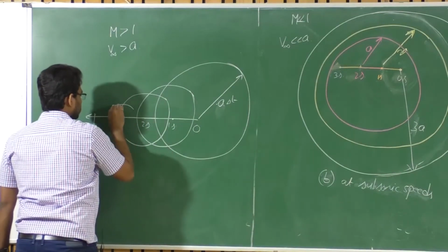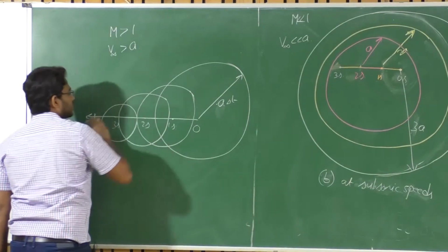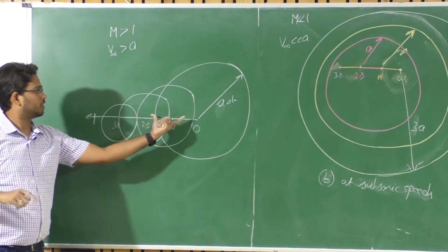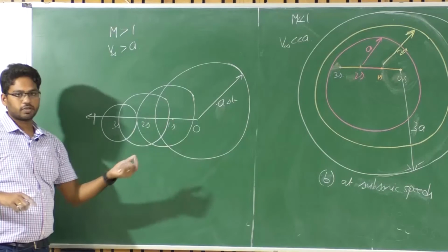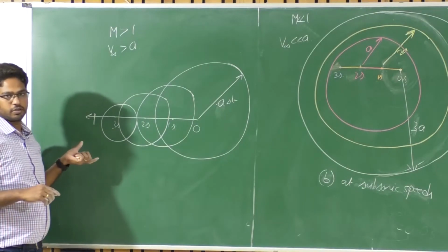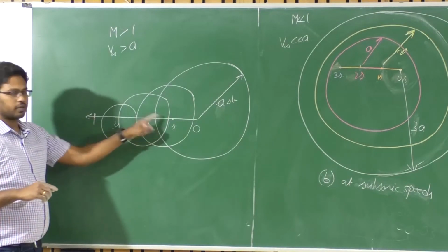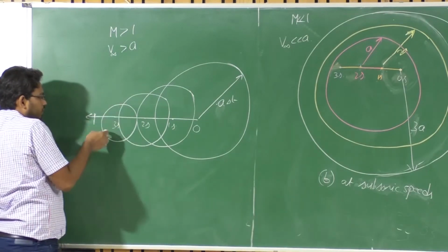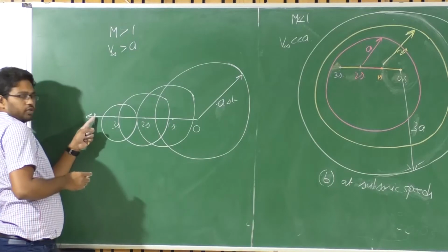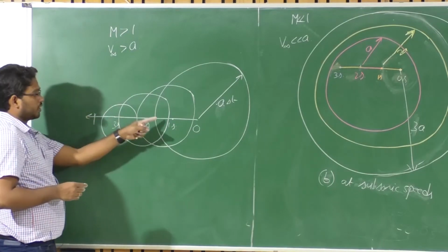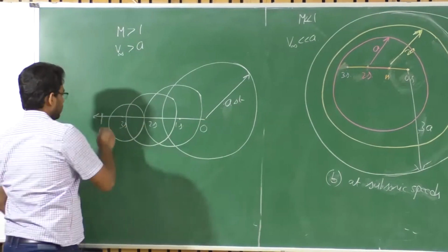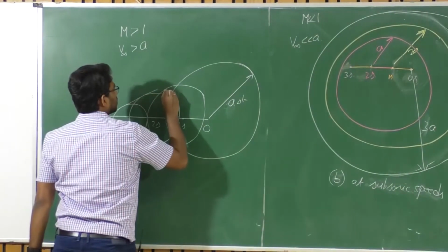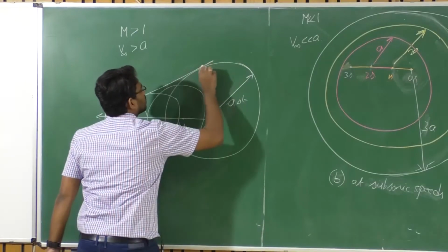And the third one again will also be velocity times delta t, right? So the diameter at each and every point will be the velocity times the corresponding time lapsed, since you have created the disturbance. Now, no disturbance will be able to overcome u, because you are traveling at a higher a compared to this. Now, let us say if you draw a tangent to all these disturbances, what you get is a